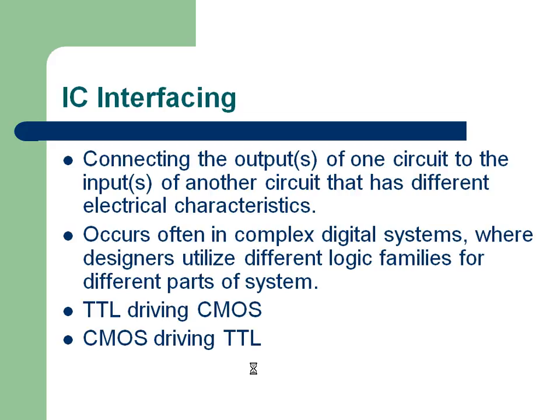Okay, now this is another topic which we are going to discuss next year, when we are talking about how to interface one chip to another chip. As long as it is a TTL chip, there is nothing great. The same issues which you talked about, fan in, fan out, can be applied here. Only thing is, now it is not the on-chip connection, it is an off-chip connection. The PCB track length and its resistance you also have to account for slightly. Ideally on-chip fan out is 10, but when it is off-chip on PCB, fan out may not be 10, because the track length on PCB will have some resistance. Only that much will differ, nothing else.